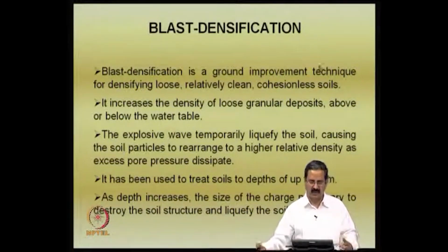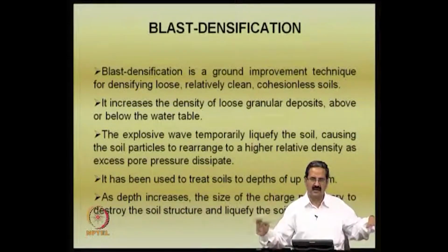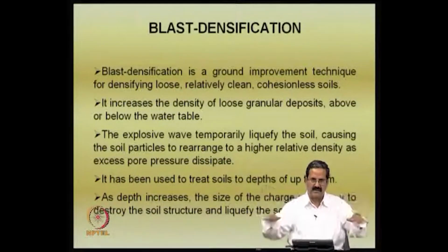Of course it is more about removal of water only. It densifies relatively clean, cohesionless soils. It increases the density of loose granular deposits above or below the water table. The technique is quite suitable for both. What we do is that we try to create some explosives. You introduce blasts, like there is some 10 meters of sand deposit. You put a blast some 10 meters down, then trigger it, and the whole area settles.